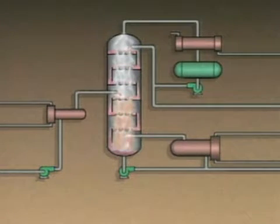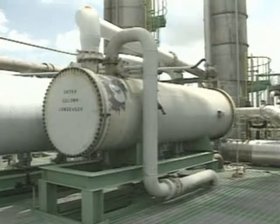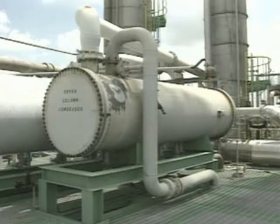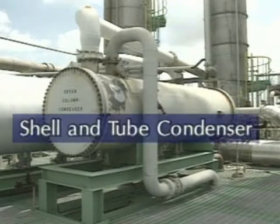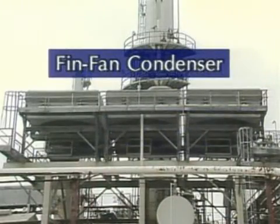For example, heavier uncondensed vapor could rise up the column, mix with the overhead vapor, and be carried into the overhead condenser. In a distillation system, a condenser removes heat from the overhead vapor and turns the vapor back into a liquid. 2 common types of condensers are water-cooled shell and tube condensers and air-cooled or fin fan condensers. Both types of condensers can experience problems.